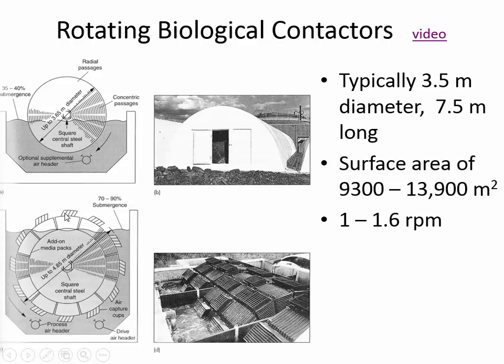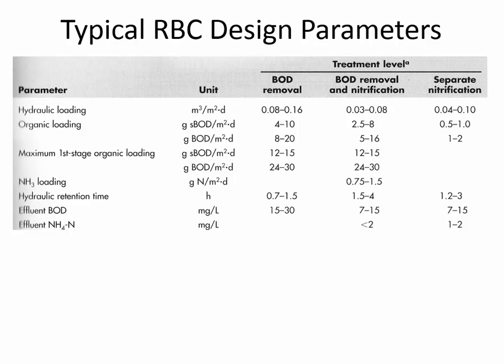But if you have it mostly submerged, then as this goes through, there are sections of it that don't get above the water surface that would be ripe for nitrification. So for denitrification, you have to have a lack of oxygen to have the conversion of nitrate to nitrogen gas. The part of the RBC down here, as this rotates around, never gets up into the air. So you could potentially control the aeration, turn it off for a period, and as that RBC rotates, have the conversion of nitrate to nitrogen gas. You could never have that same control in a trickling filter, not to the same extent.